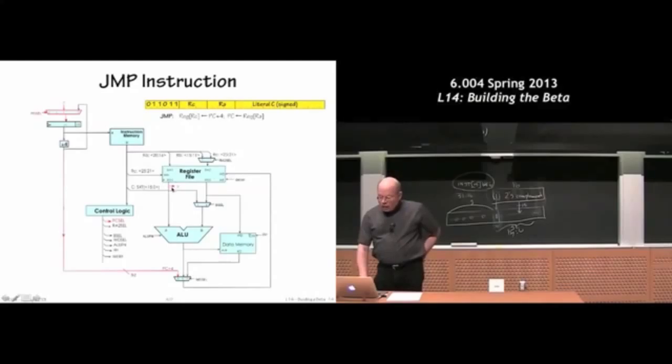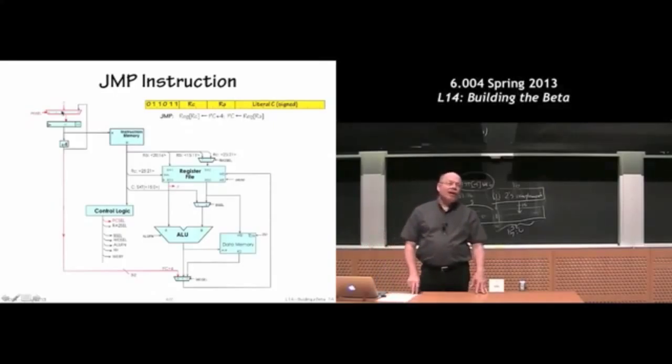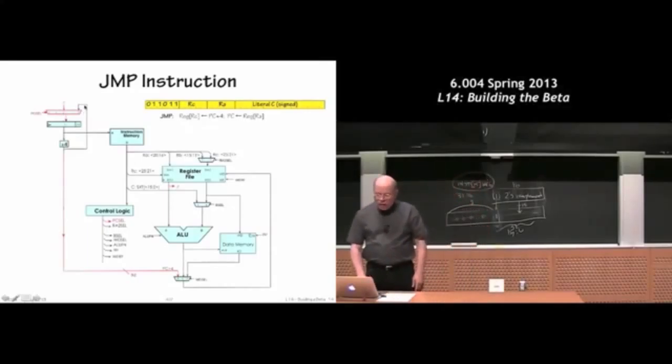In the case of a jump instruction, we basically take the contents of the RA register, and that simply becomes the new value of the program counter. So whatever was in the RA register, almost always in our programs, is the value in the LP or the XP register, so the linkage pointer. This is how we return from procedure calls. We basically just stuff that value into the program counter, and away we go. The next instruction will now come from wherever some previous branch came from.